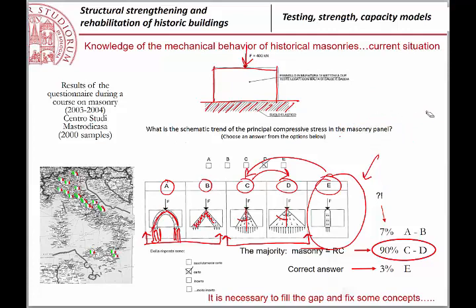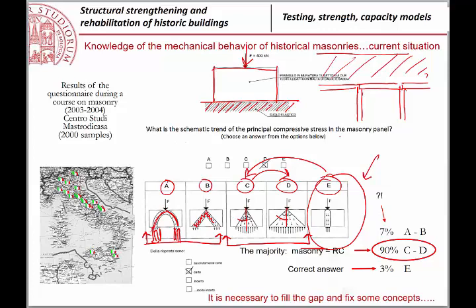For example, think about what you can have if you have columns. Sometimes you have wooden beams, okay, and then the masonry. This is not a case where the foundation of the wall is rigid, because this is a wooden beam, okay? I'm talking about, of course, the upper part. So the beams are, in some sense, the foundation of that wall, but they are not rigid.